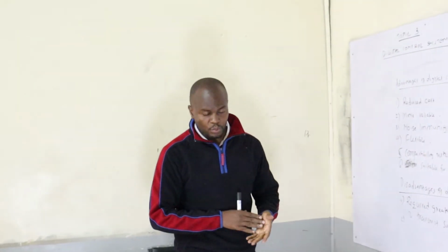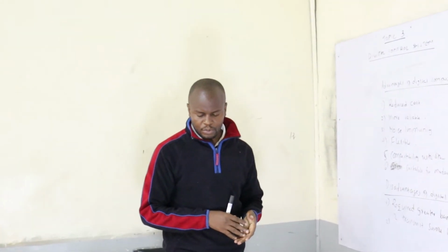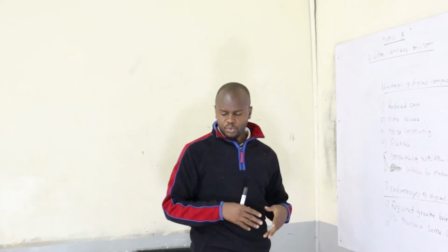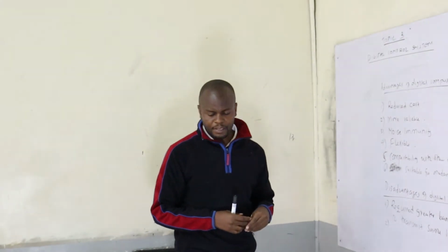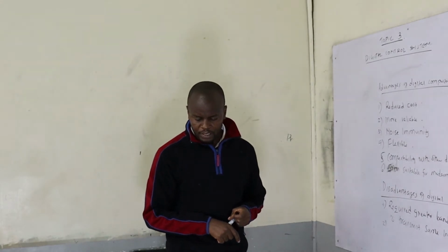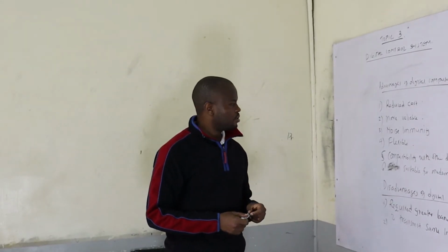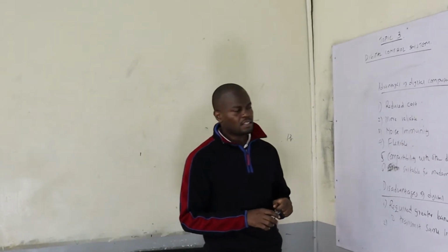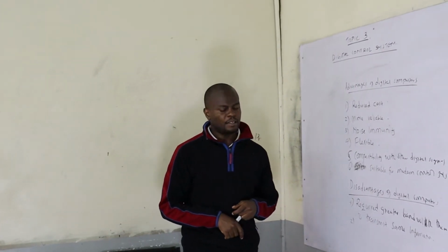This brings about a delay between the analog input voltage and the output digital word. In the ADC, the analog signal is first converted to a sampled signal and then to a sequence of binary numbers, which is the digital signal. The sampling rate must always be at least twice the bandwidth of the signal.